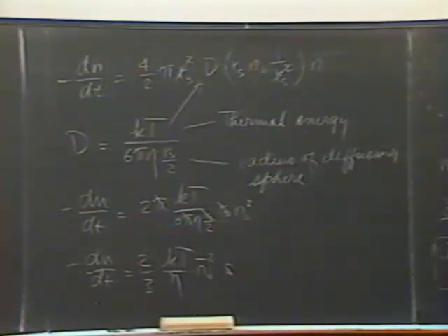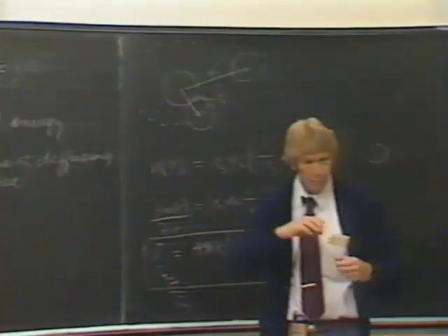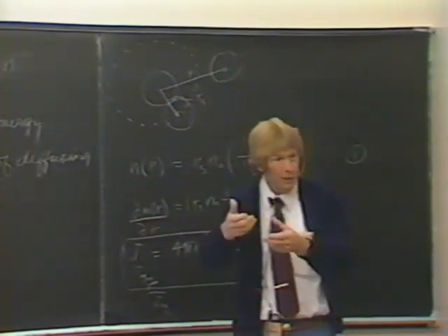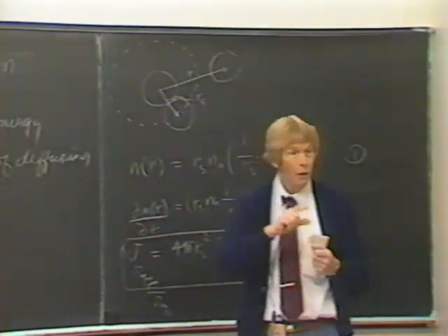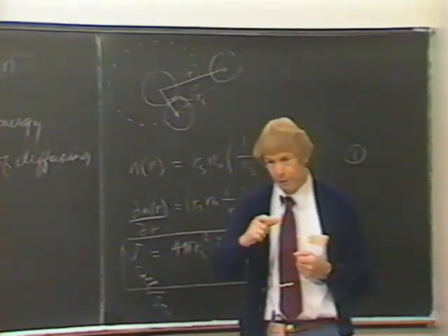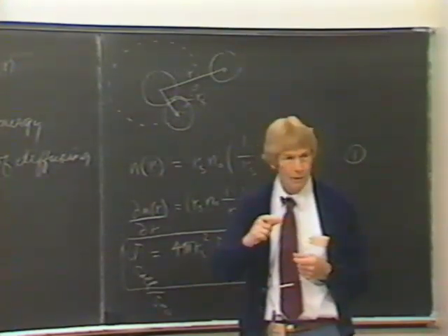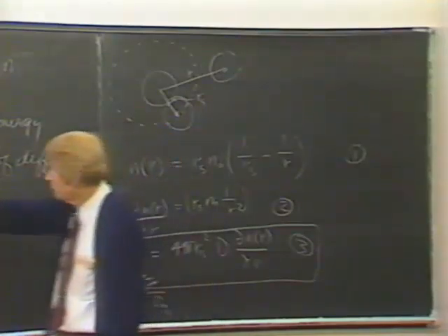Remember I pointed out that Brownian motion is rotary in nature. That is, the particles rotate as well as translate. So you use the longer dimension for the collision radius, and you really should use the smaller dimension for this one. Clay particles are platy, remember? They're not actually spheres.